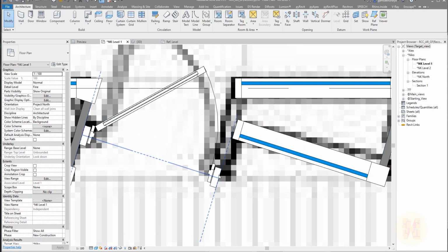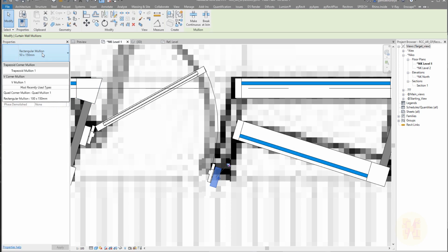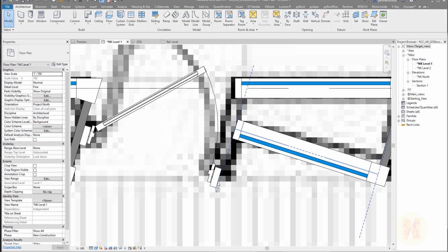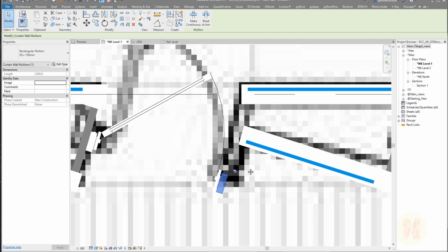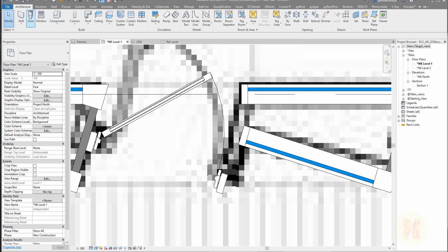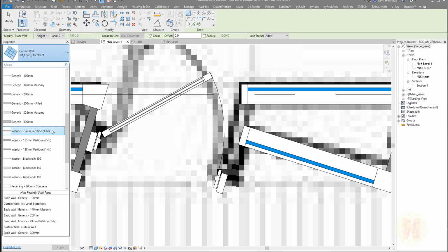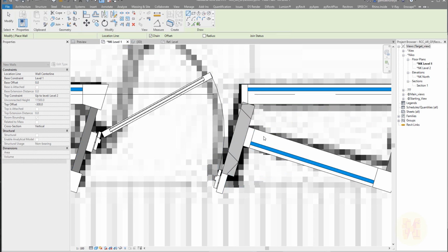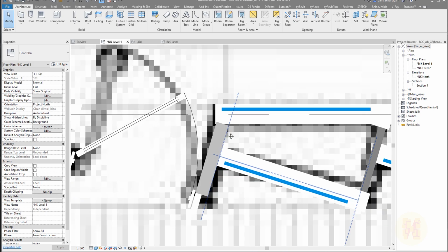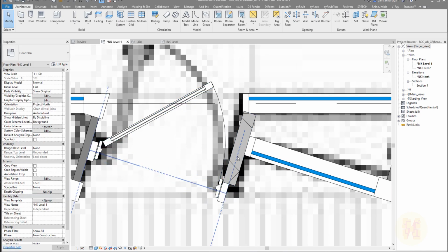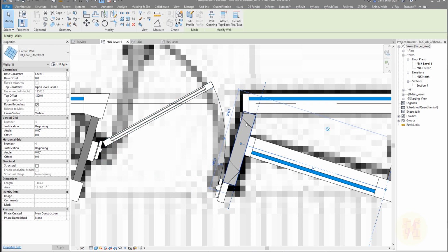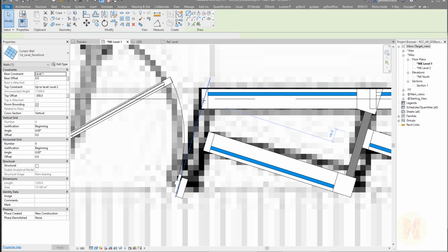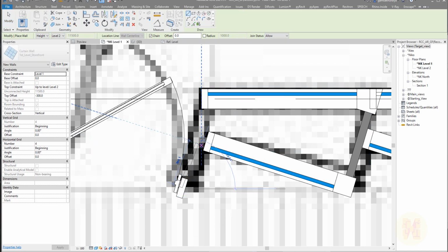Yeah, that's right. Let me select this part and unpin it, and I will change it to 100 millimeter. And as you can see, it's changing inside of that. This is really terrible for us. So we should somehow change it. But I think we will just create the wall here, the 100 millimeter, like this. Let me check first. Oh, not wall. We will do one more curtain panel here, the curtain wall. Let me connect it, and I will create it from this part.